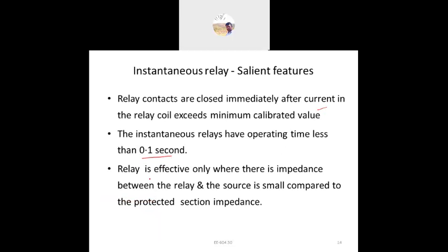So one thing to remember: the impedance between the relay and the source is small compared to the protected section impedance.